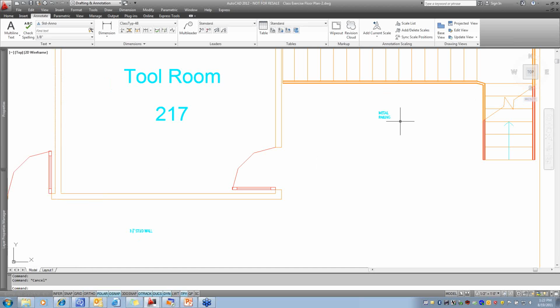But its placement may be a little off because it may be too far away from what I actually want to label. If I select this text, I can move the individual instances of this text at its assigned scales independent of the other text items assigned to the different scale factors.